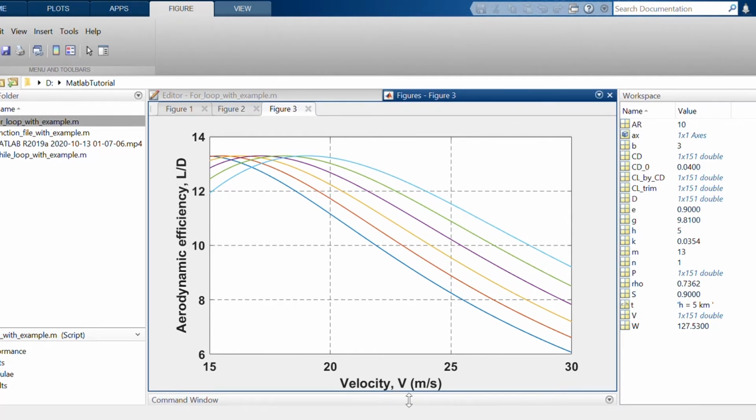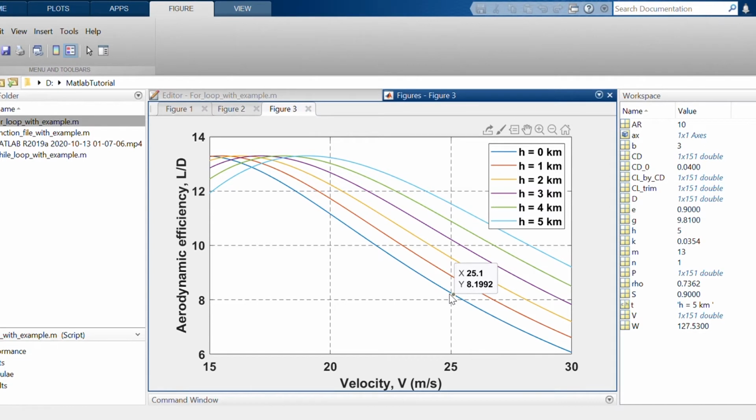You will see these are very important parameters like aerodynamic efficiency. At 5 kilometer, your aerodynamic efficiency is almost 11.4. Okay, and at sea level, your aerodynamic efficiency goes down to 8.11. Okay, and this flat line is independent of flight speed, because as you know, CL equal